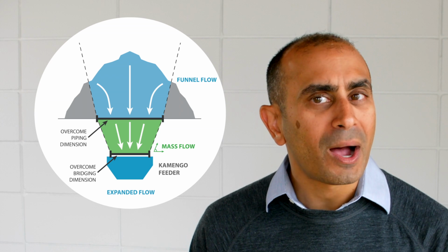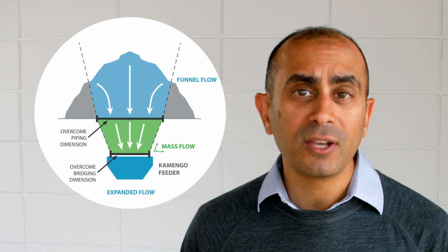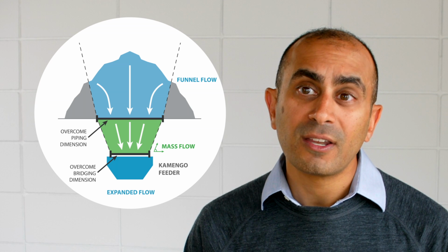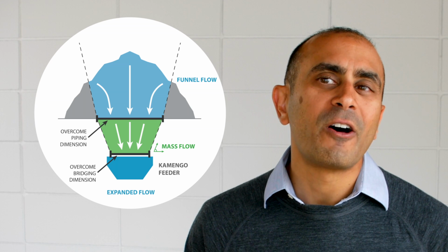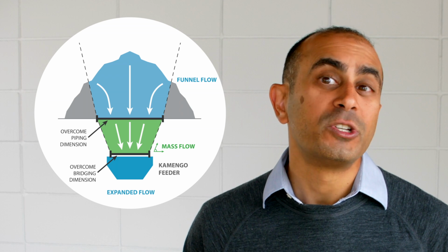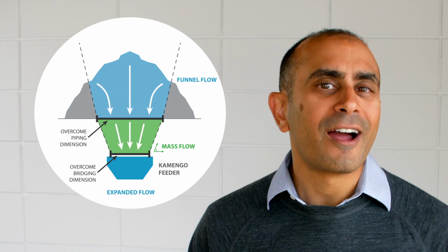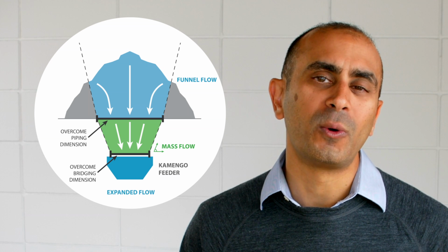Expanded flow is a very powerful tool when designing large storage applications handling difficult flowing materials. By combining a mass flow segment with a funnel flow segment, you get the best of both flow patterns to achieve designs that neither could effectively do alone.